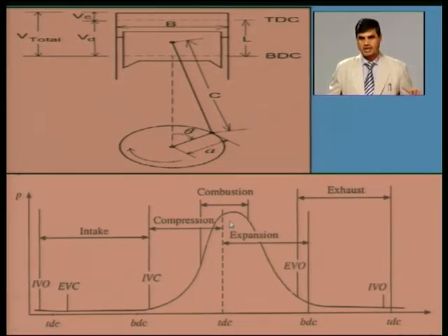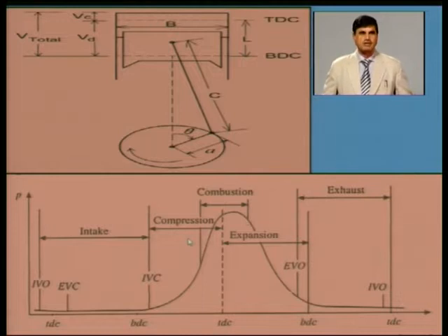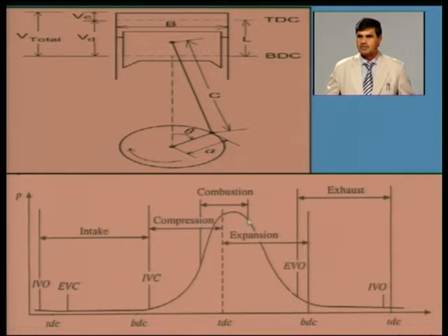So in the theoretical cycle, if you remember, in the case of the Otto cycle we said heat addition is at constant volume, meaning without consuming time, heat is being added theoretically. But in the actual cycle, for the purpose of combustion, some significant time is needed, 40 to 45 degrees of crankshaft rotation. Yes, this is the combustion duration, and one of the reasons for lower efficiency in engines,